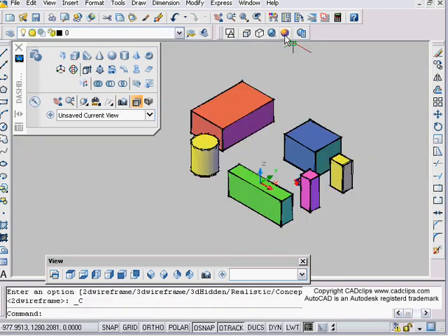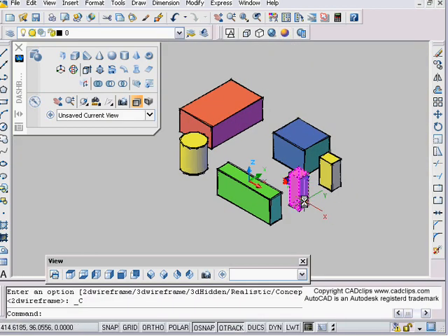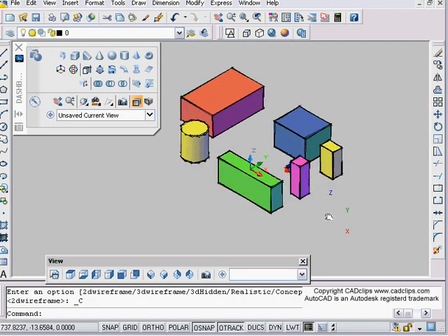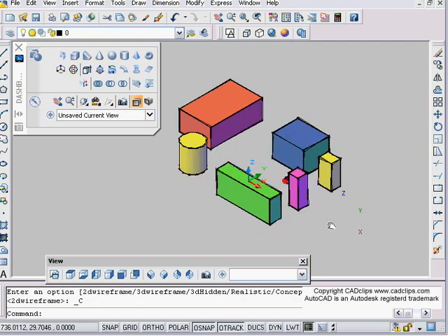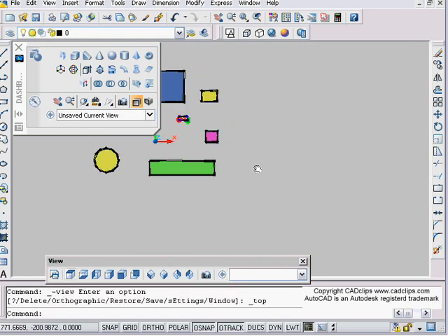I'm going to switch over to the conceptual view, for instance, and cameras are pretty easy. You just drop them in and look. The thing about a camera is it has a camera height and a target height, and then basically it looks in that direction, and we have clipping planes which we can turn on and off with our cameras. And I usually find that setting myself to a plan view